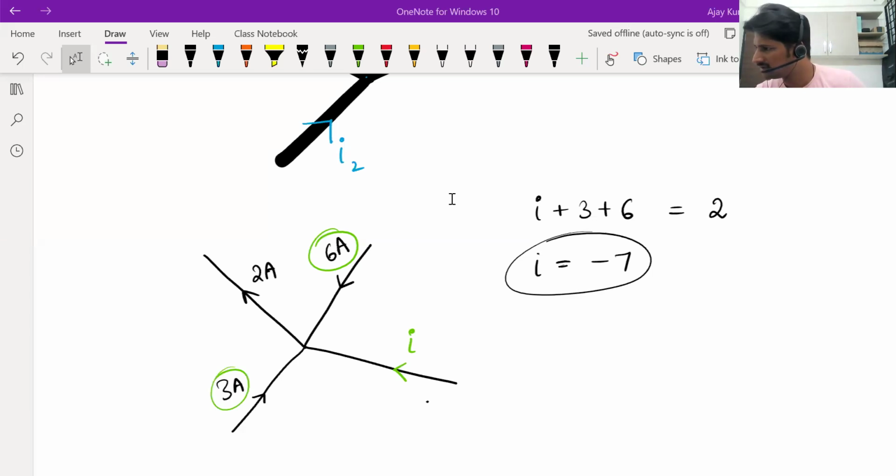It's written, input voltage. Okay, this is a laptop charger. It's written input is 100 to 240 volts. We know in a household power socket, we get 220 to 230 volts. So input is that much, and current is 1.5 ampere. Output voltage is 20 volts. The laptop adapter is giving an output voltage of 20 volts. 20 volt is safe for us, we can touch that much voltage, not an issue. And output current is 2.25 amperes.